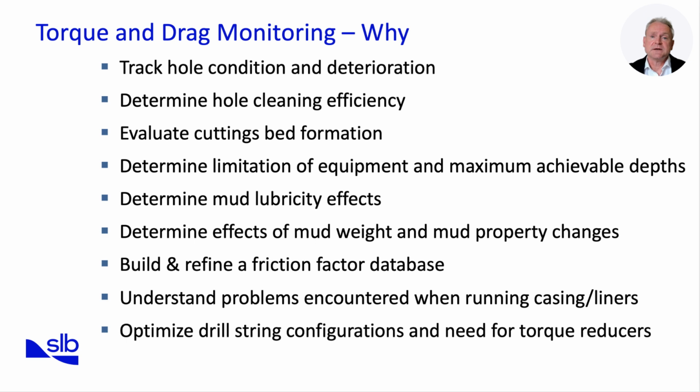Poorly cleaned wells allow cuttings to settle and form beds, which dramatically increase drag. Torque and drag trends provide a direct measure of how well the mud system and circulation practices are keeping the wellbore clean. Monitoring also helps determine the limitations of equipment and maximum achievable depths. As torque and drag rise, the effective reach of the drill string is reduced. Identifying these limits allows engineers to decide whether trajectory modifications, mechanical aids, or lubrication are required.